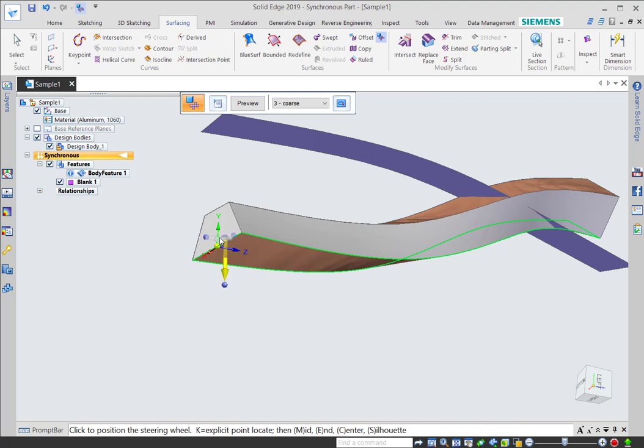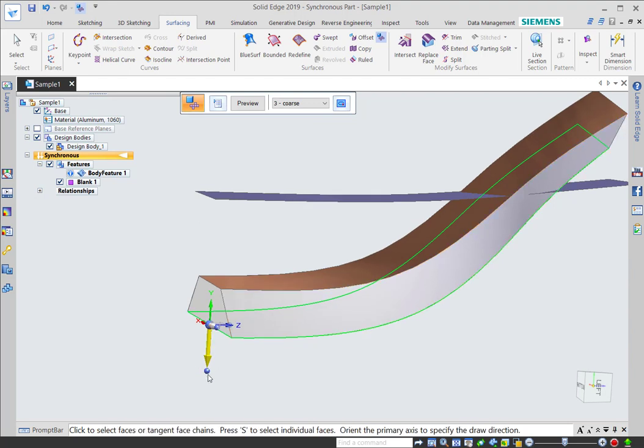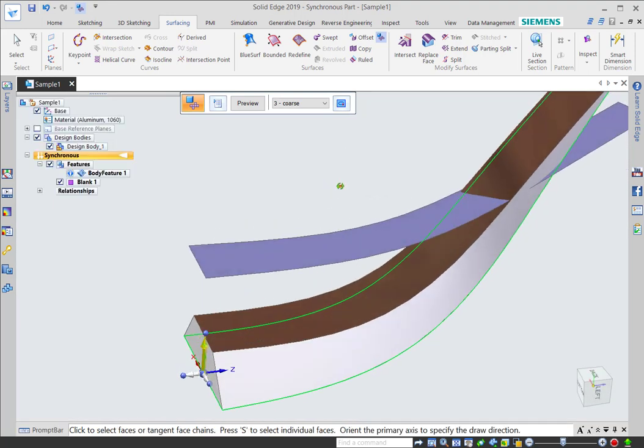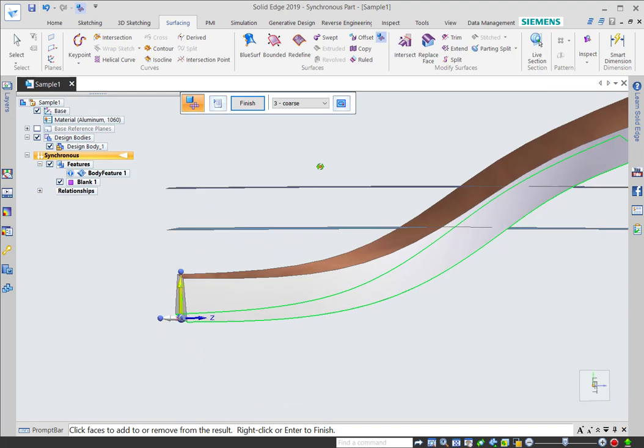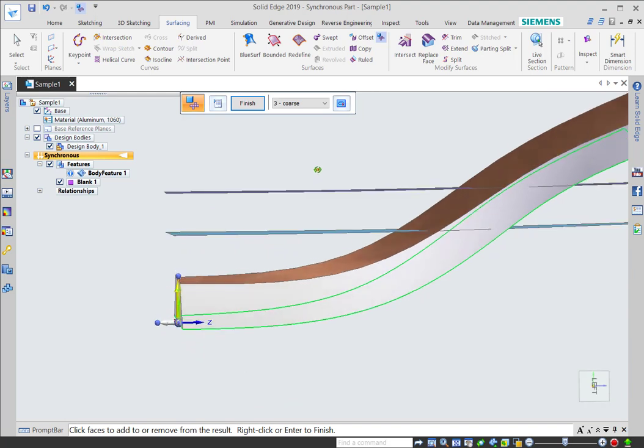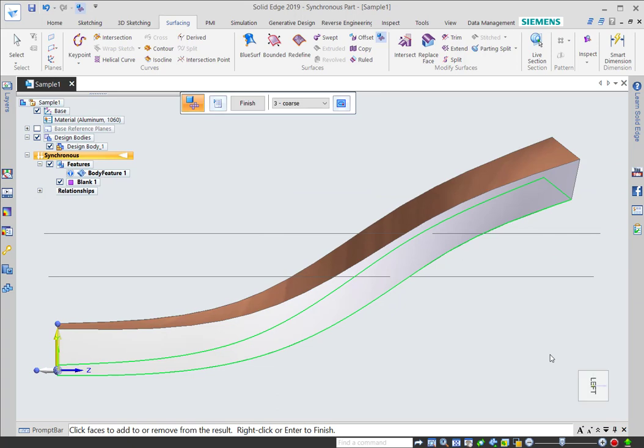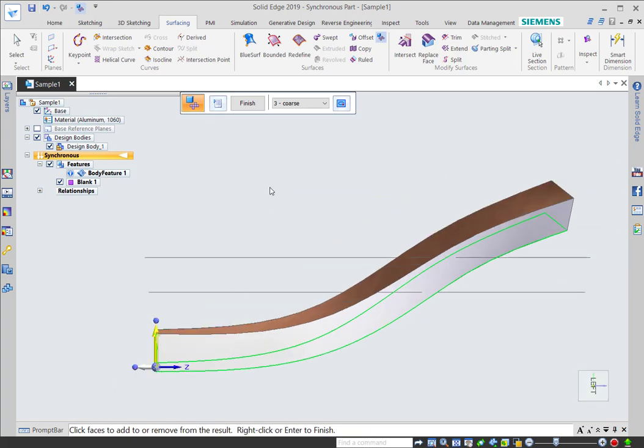and I'm going to put this guy here. I'll hold my control key down, click the little knob, and flip that 180. So it's kind of important that they both be pointing in the same direction, so that you'll see that the thickness should be really close to what the original thickness was, as long as I keep that directional arrow the same.